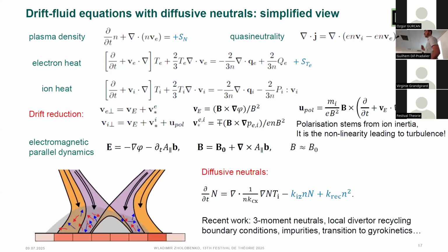Again, my question is this: your boundaries are not simple, right? They are curved boundaries. Yes. So how do you impose the boundary conditions? Say, even if you want to impose no slip, or when you say we impose sound speed, how do you do that? That's a very good question, but I probably do need a couple minutes to answer it. We use penalization in practice to deal with the complicated shape of the boundary conditions. Not sure if you're familiar with immersed boundary technique. Yes, we're using immersed boundary. Okay. And if you want to know more, I have some backup slides, but we'll need some minutes to get through them.